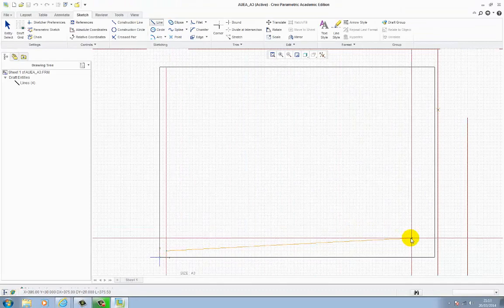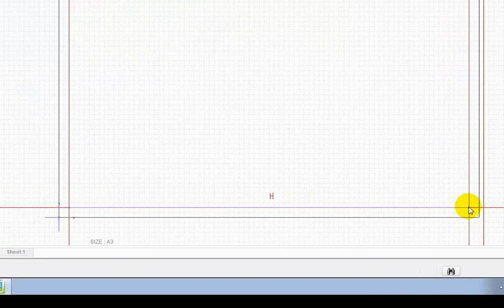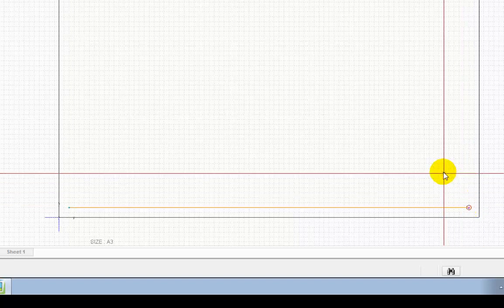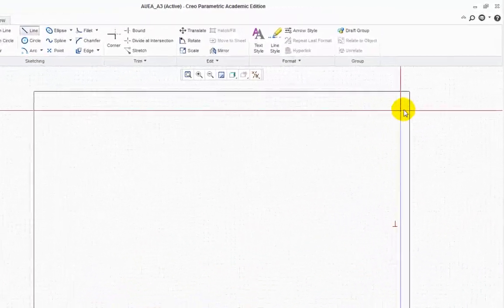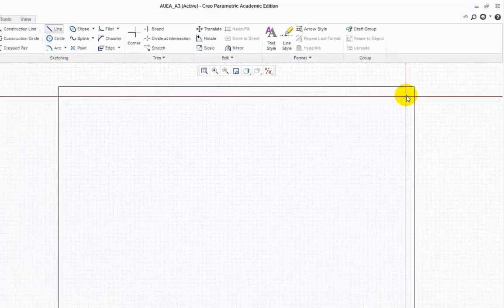Bring the cursor across. Make sure it's horizontal and 2 grid spacings from the right hand edge. Left click again. This is different to using the normal line command in Sketcher, left clicking just completes the line and doesn't restart the next part of the line. Bring the cursor back over the endpoint, left click again. Bring the cursor up. This time it will stop 2.5 grid spacings from the top of the page. Left click again. This completes the line.